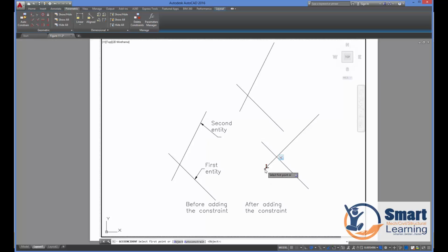So with respect to this point, I need to match this one. Here we applied one coincident constraint, where you can see the end when I hover my cursor, and one perpendicular constraint. We applied both simultaneously to cater to our exact requirement: how to reshape and give the exact position, orientation, and location based on this particular geometric constraint.